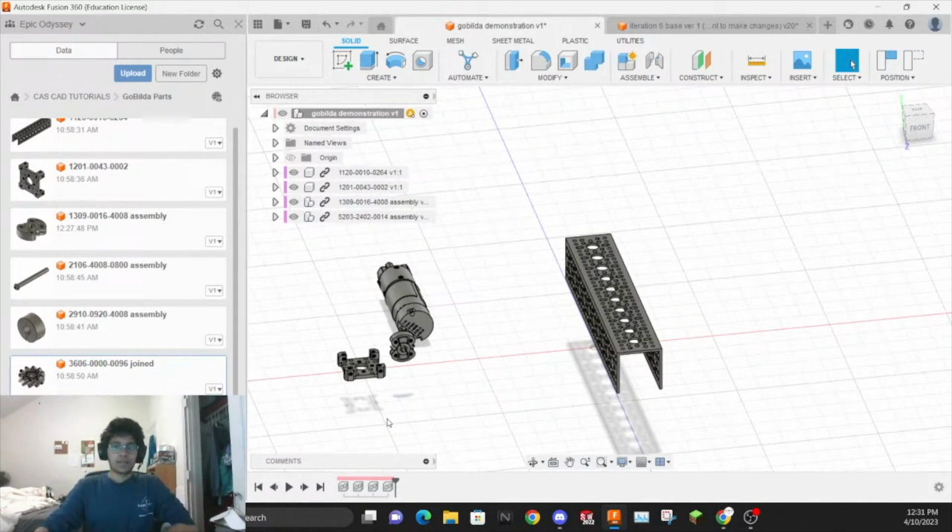So that tends to help programming a lot, but you can also use gear drives, which are just like two bevel gears. If you know how bevel gears work, then this is a very easy explanation. Basically, a bevel gear is a gear that sits like this with angled teeth. And you can sit another bevel gear on top at 90 degrees and it translates rotational motion.